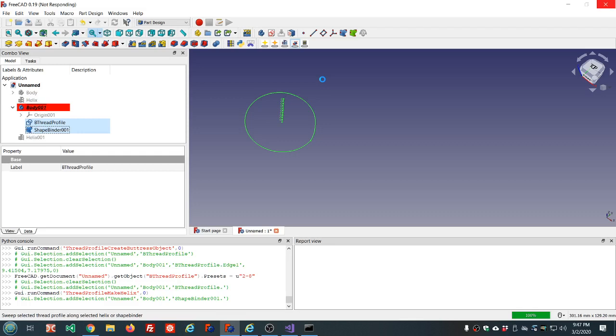So these buttress threads are designed as kind of a one-way thread where the strength is focused in one direction, so it's not as strong in the other direction. This can be, I think, good for 3D printed threads because they're already kind of weak because of that plastic material. So if you can focus the strength in the direction that you needed the strength in, which usually is just one direction, you can maximize the strength of the thread.